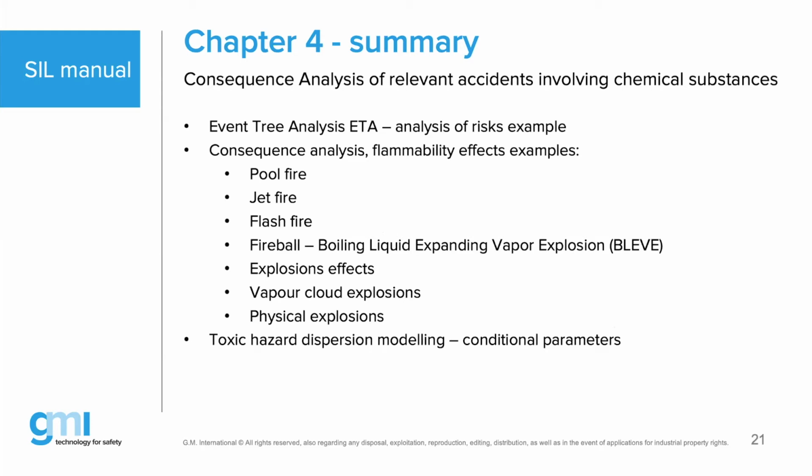In this book, in chapter 4, they talk more about the consequence analysis, and they give you event tree analysis. Event tree analysis is a technique which starts from the given event, and it will analyze what type of consequences it will have, and there we come in with the frequencies of these consequences. So for those experts maybe listening in to this webinar, event tree is actually the basis for any LOPA that you may have used already in your projects.